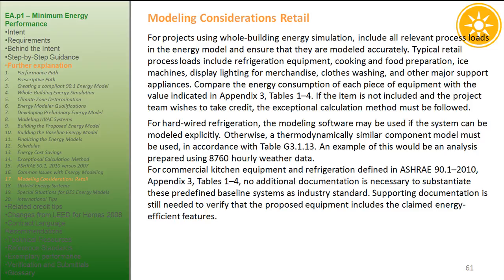For commercial kitchen equipment and refrigeration defined in ASHRAE 90.1 2010, Appendix 3, Tables 1 to 4, no additional documentation is necessary to substantiate these predefined baseline systems as industry standard. Supporting documentation is still needed to verify that the proposed equipment includes the claimed energy-efficient features.